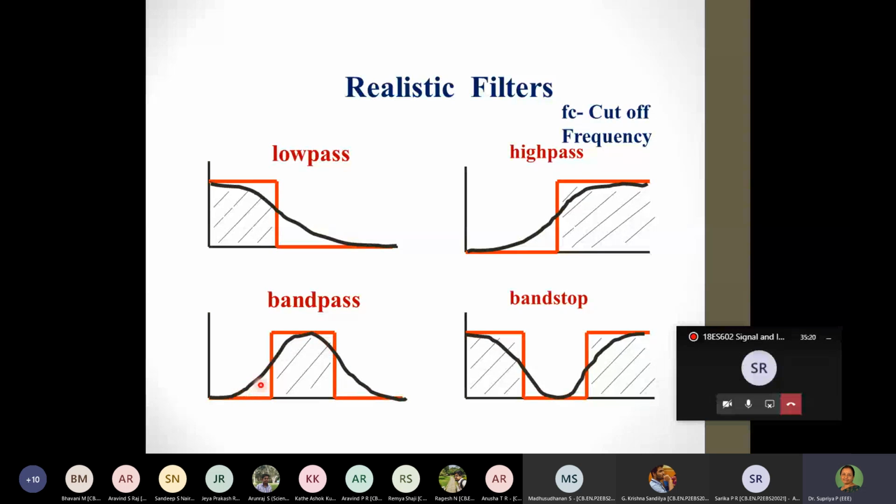It allows some low frequencies to pass through, and in the same way some more high frequencies than our chosen FCH and FCL. The same thing with band stop. We are allowing only certain frequencies to pass through, but you will see that some more frequencies are getting through. Similarly, here we are cutting at some high frequency. In our example we had considered 200 hertz. It may start getting cut at 180 hertz or so. That is what is called a realistic filter.